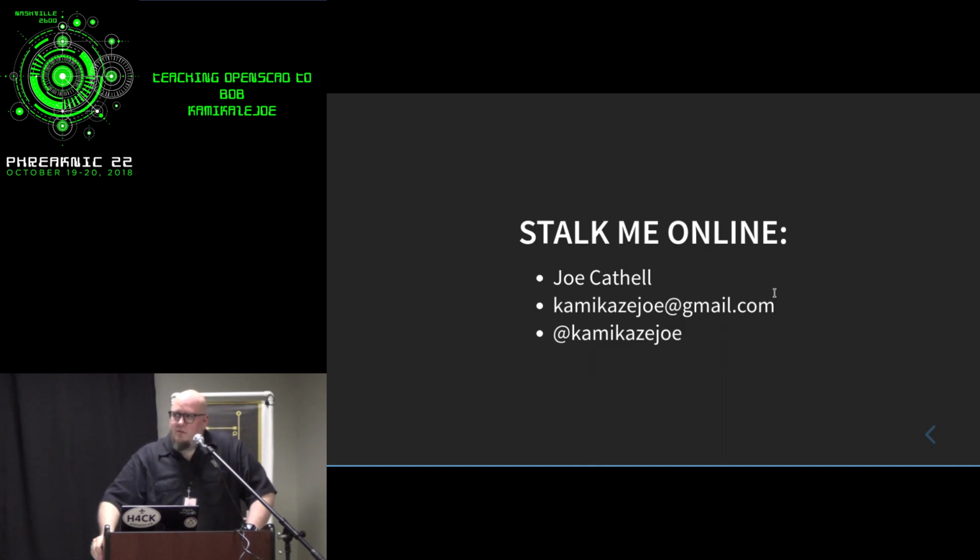If you turned the cylinder into a 6-sided cylinder and then made an infinite grid of it, couldn't you also make a lattice of 3-sided, 4-sided, 5-sided, 7-sided, etc.? Oh, you mean instead of a 6-sided cylinder? Yeah, you're just changing that $fn value, it defines the minimum number of polygons that you're supposed to use. So if I say 6, it's 6, and yeah, you're absolutely right. That would work with anything.